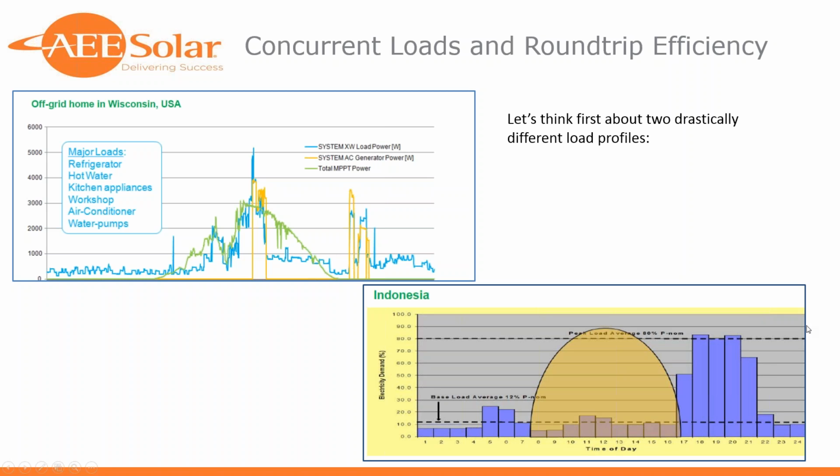On the other hand, this case down here is a rural electrification project in Indonesia, but I think similar projects occur everywhere in the world where our peak loads are actually occurring later in the evening, so essentially after the sun has gone down. So in an area where most of our loads are lighting and home appliances, this would be fairly standard. So this one is an example where essentially the building or the site is unoccupied during the day, or the loads are not electrical in nature. So in this instance, you've got non-concurrent loads.